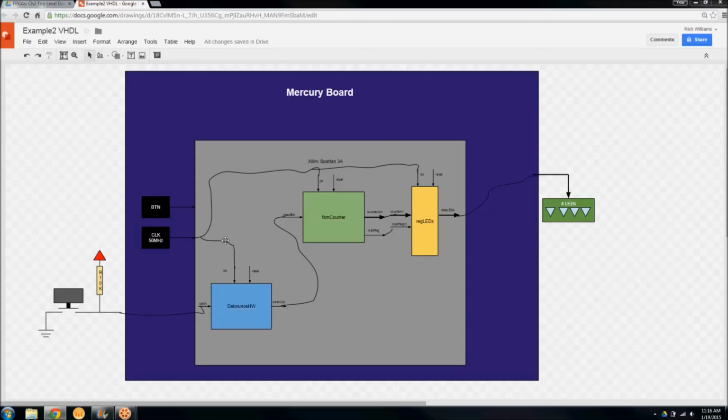And as we were talking about before, the 50 megahertz that is getting fed into this debounce hardware is just way too fast to accurately verify whether or not this button is stabilized. So we're going to have to build another tiny module that takes in the clock input here, and then outputs a significantly slower clock signal, which is going to get fed back into this debounce hardware. And that clock is going to be slow enough that the S debounce signal inside this hardware will be able to verify for at least around 10 milliseconds whether or not this button has been stabilized, either high or low.